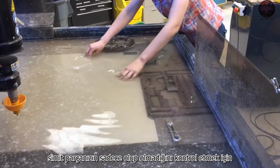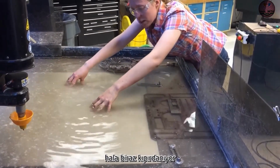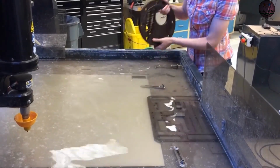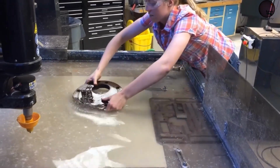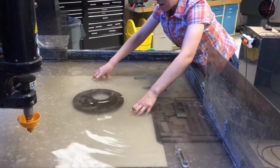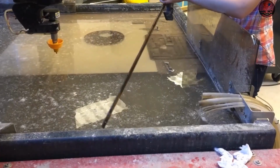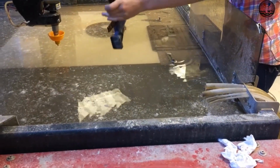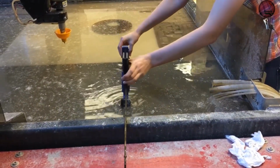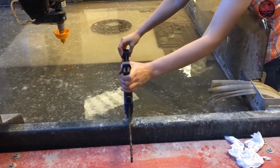A good way to check if your part wiggles is to just take your fingers and tap on it. There's still a little bit of wiggling in the middle, so next I'll use this weight, big weight, and I'll set it right here. And now my part doesn't wiggle at all. Another way to secure your part is to use one of these clamps. So you can bring it in, fit it almost all the way, and then squeeze it until it's tight.